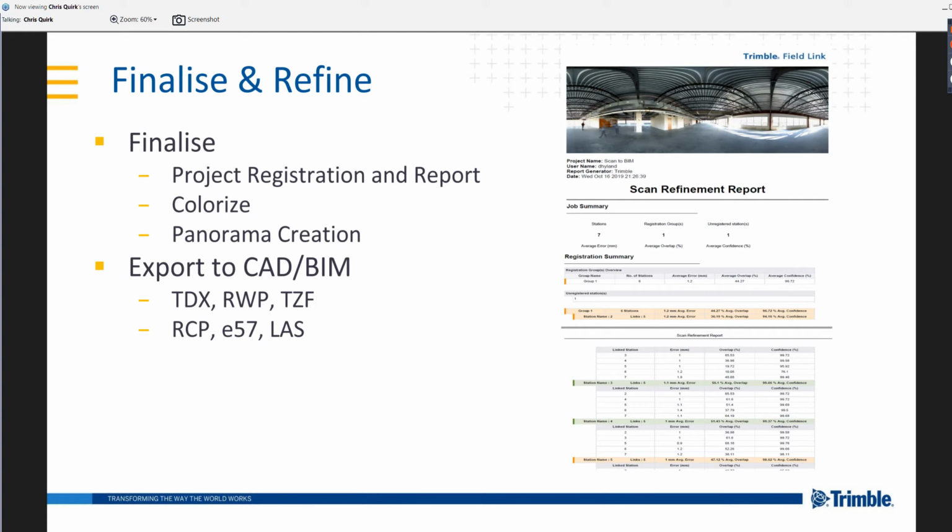And what that's going to do is it's then going to go through every single station scan, and it's going to stitch them together and tighten them up. And it's going to give you a nice report to say how accurate your scan is, the residual error, just like you get if you were working in something like Trimble RealWorks.